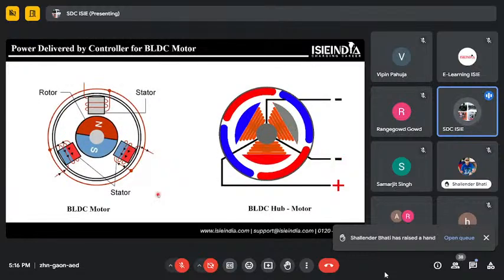As we talked about BLDC motors, they are brushless DC motors, a highly advanced motor which has high initial torque and high running torque, and these are motors which can't run without controllers. So we need inverter connections and AC-DC conversion. All these motors work on the trapezoidal wave signals coming as output from the controller. So you can see the wires that we are getting from the commanding point of view.